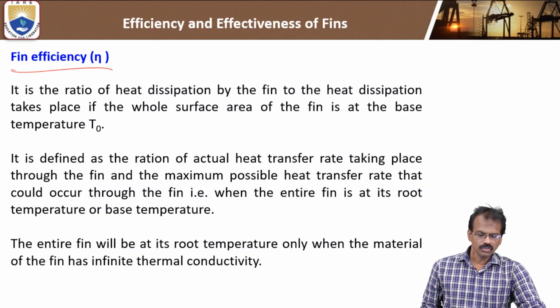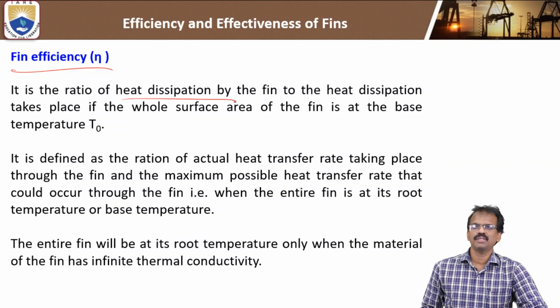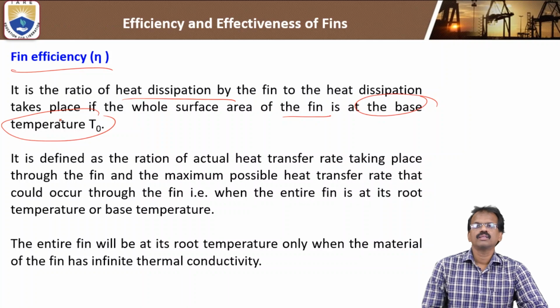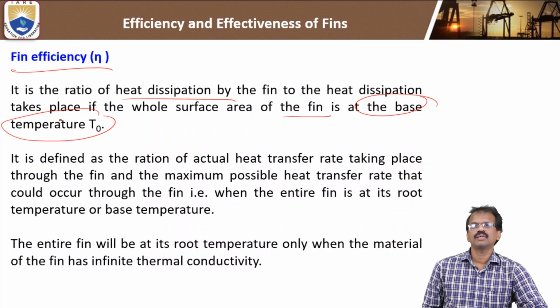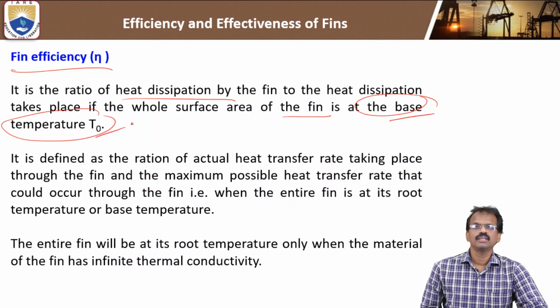It is the ratio of heat dissipation by the fin to the heat dissipation that takes place when the whole surface of the fin is at the base temperature. It means we have to consider the temperature T0.